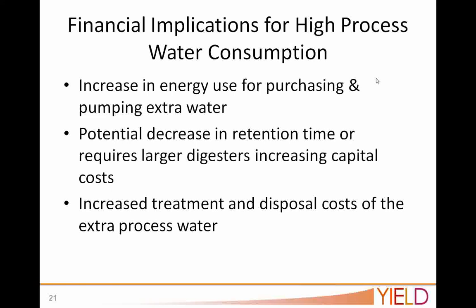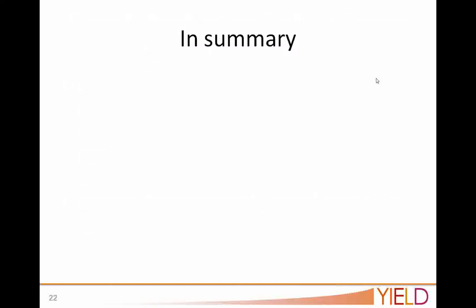Again, you can recycle some water, so recycling digestate, but it can only be done to a certain point. Generally, the limiting factor is nitrogen load, and if you've got a lot of meat or high-protein material in your feedstock, then you may not be able to recycle as much as you thought, because you will ultimately have an accumulation of nitrogen, and so there's a limit based on the nitrogen balance of what you're trying to do here.